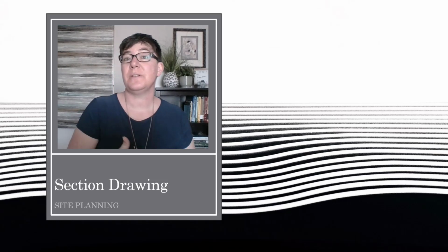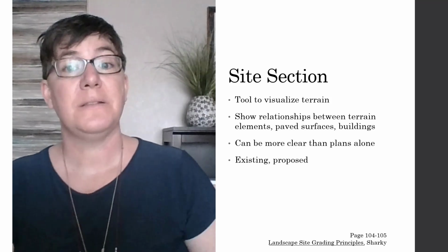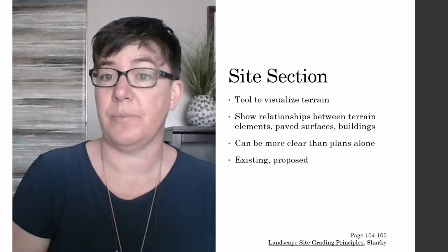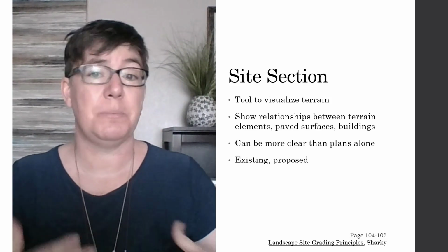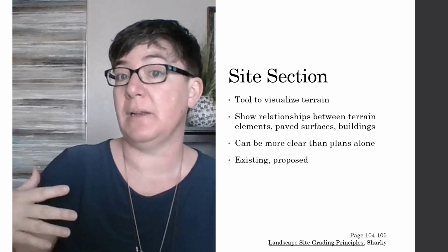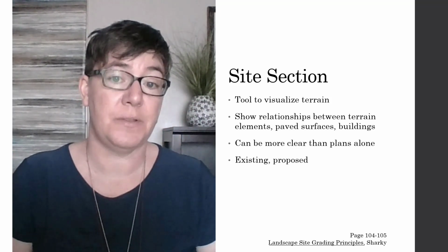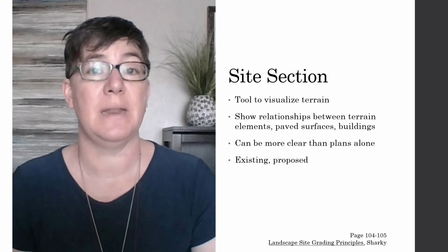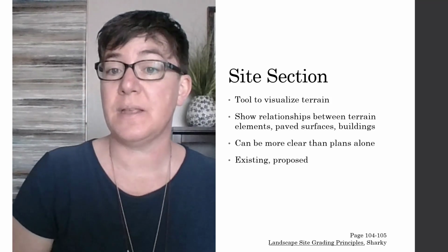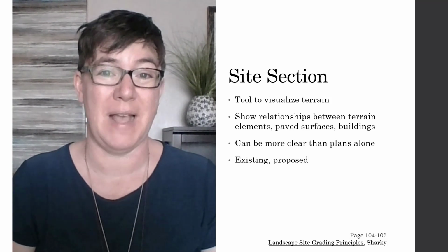In the last video, you just looked at a section through a landform. A site section is a common tool to visualize terrain. It can show relationships between the different terrain elements, between the paved surfaces, the buildings, etc. And the section can really help us understand. It can be more clear than the plans alone. You can prepare a site section for an existing site and also commonly for a proposed design.